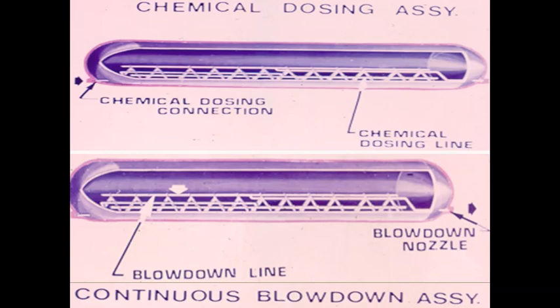disodium and trisodium phosphate dosing, as well as a continuous blowdown arrangement to maintain the silica concentration within the drum water, so that silica is not carried over with the steam separated at saturated condition, because at lower pressure silica gets separated from the steam and may attach to turbine blades, thereby creating problems of vibration.